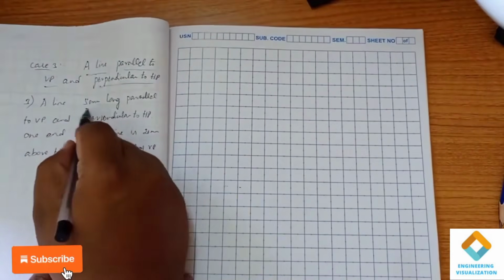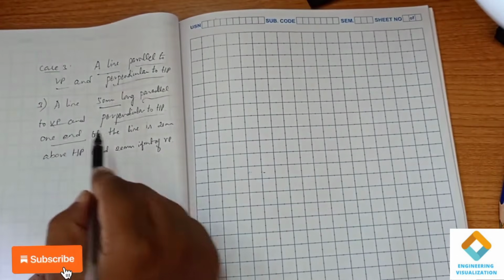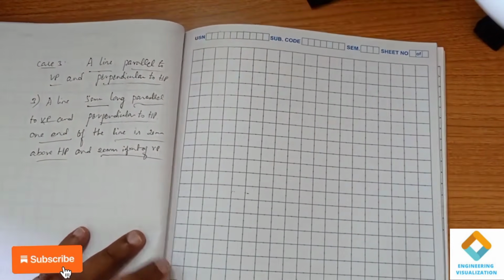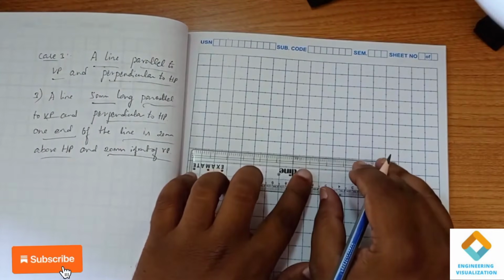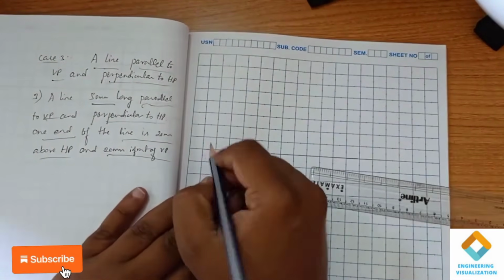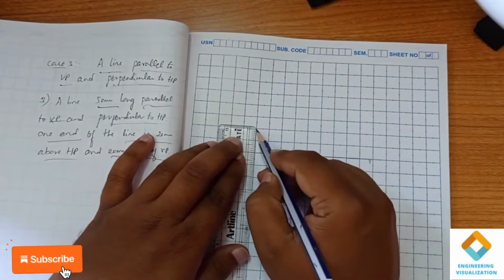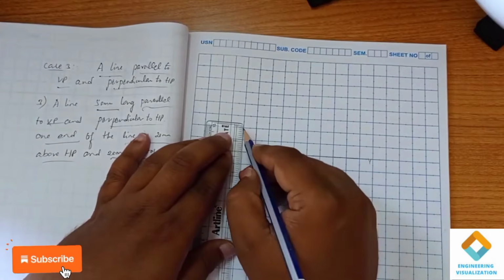We have to draw a line of length 50 mm. It is parallel to VP and perpendicular to HP. One end of the line is 20 mm above HP and 20 mm in front of VP. So first we are going to draw an XY line here. VP, HP and Y. Here both the ends of the line are at a distance of 20, so we can show the dimensions on one side.